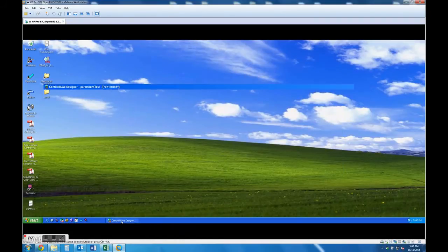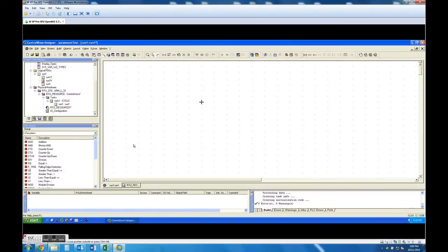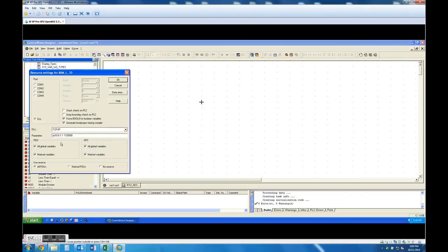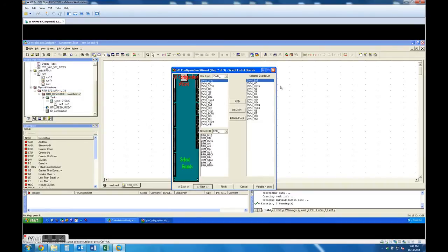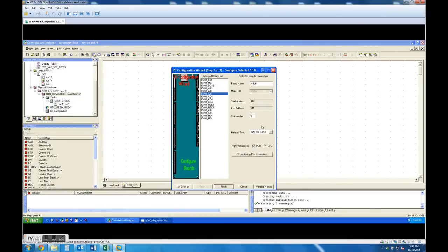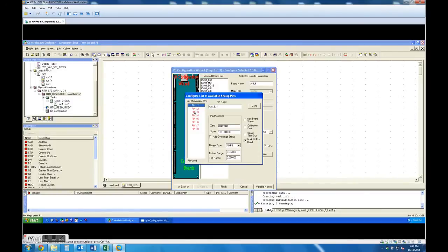ControlWave Designer. ControlWave Designer offers several different methods for generating and debugging control strategy programs, including function blocks, ladder logic, structured text, etc. Various communication methods are offered, including TCP/IP, serial links, as well as communication to OpenBSI software and networks. The I/O configuration wizard allows you to define I/O in the ControlWave series controllers and configure the individual mapping of I/O points for digital and analog inputs and outputs.